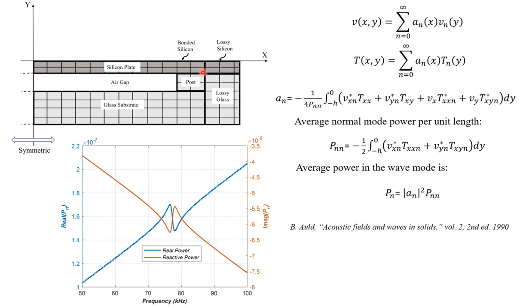But this does not mean that when the silicon plate is harmonically excited by a time varying signal, it does not couple the energy. Well, the AC particle velocity is not zero. So that boundary condition does create dispersive waves into the backing medium, which is a glass substrate in this case. So these meshed elements are that of glass backing. To the right, you see a lossy glass.